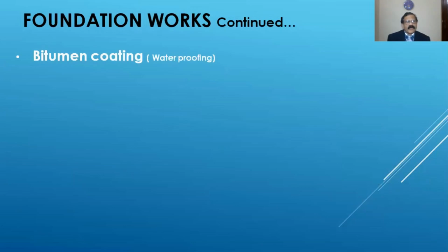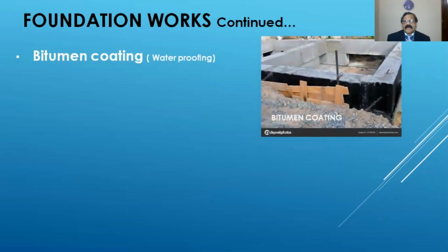After this, you have to do bitumen coating for the foundation work. This is just to protect the foundation from water or other chemicals. Then you can do the backfilling, that is filling back.